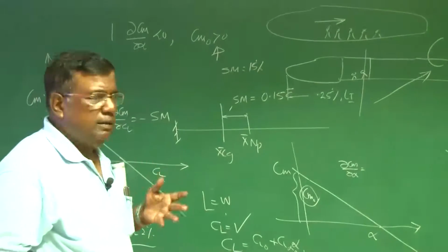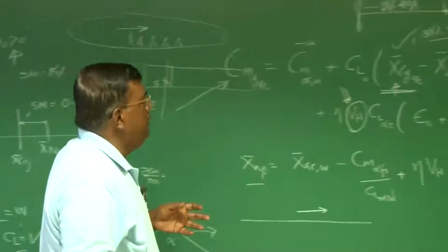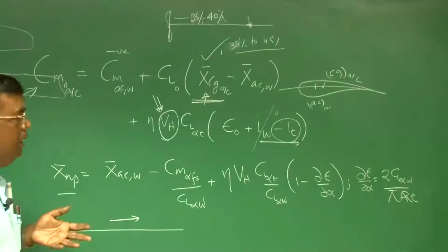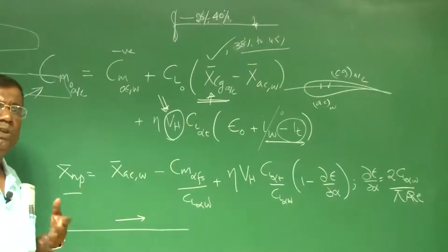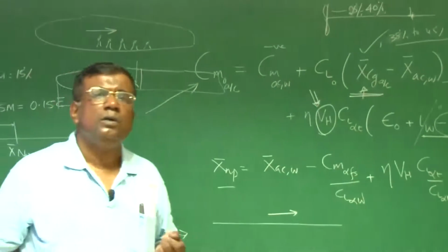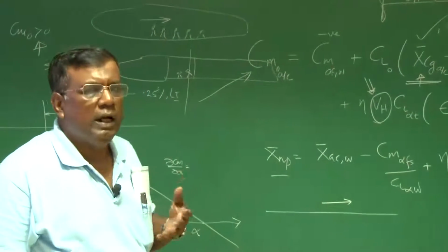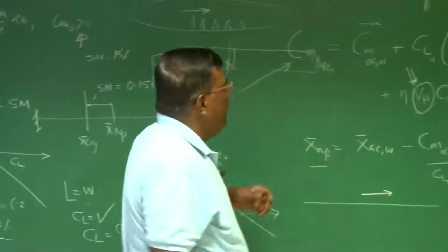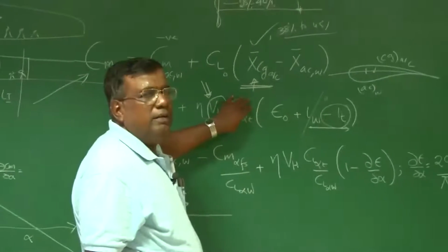We generally use a symmetric aerofoil for the tail, but its aspect ratio should be less than the wing aspect ratio, just to ensure that the tail stalls later than the wing, right? These things you know. I also have a fairly good idea about this number, right?